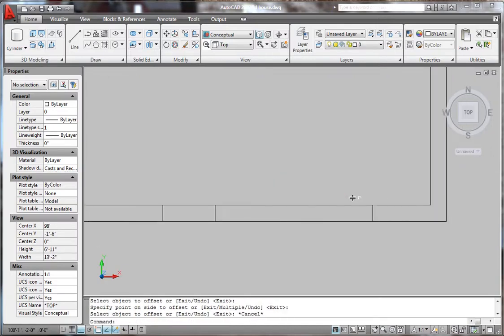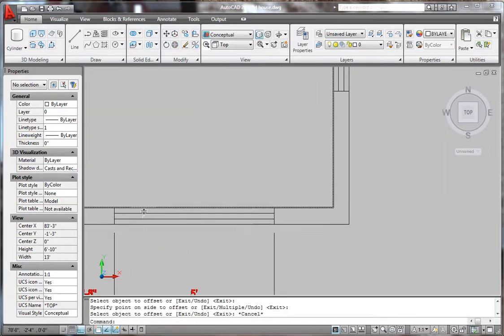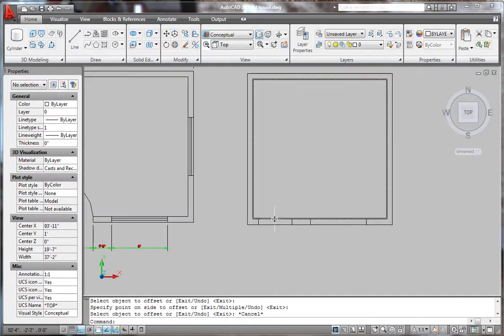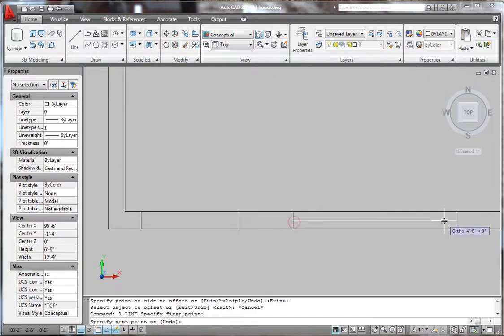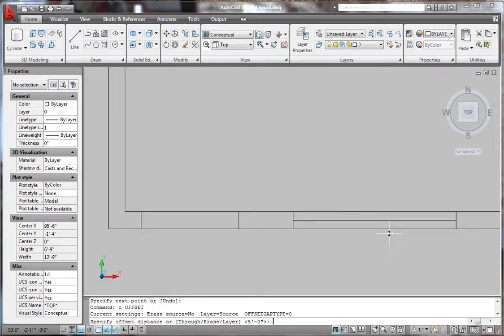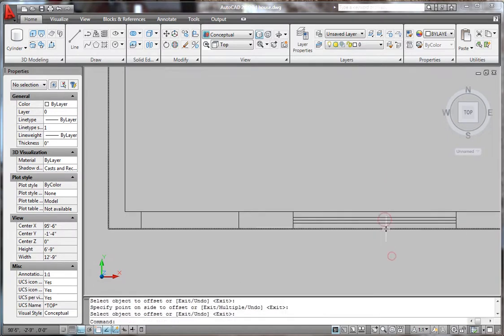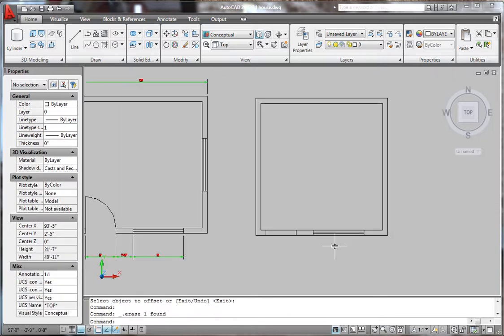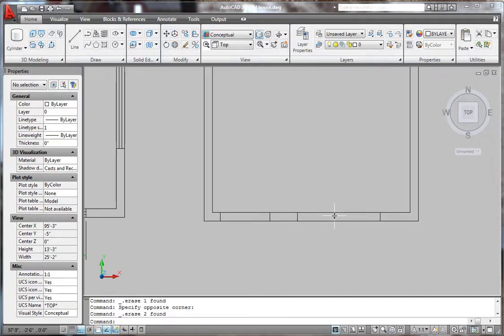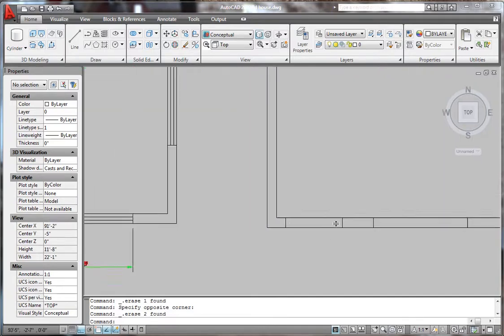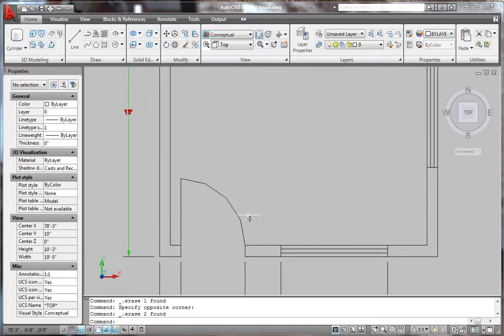You can add these lines to show it as a window, like select a line from midpoint to midpoint, offset 1 inch to each side. But we don't need these lines now because we have to use press pull command to convert it in 3D, and also we are not going to create this symbol for door.